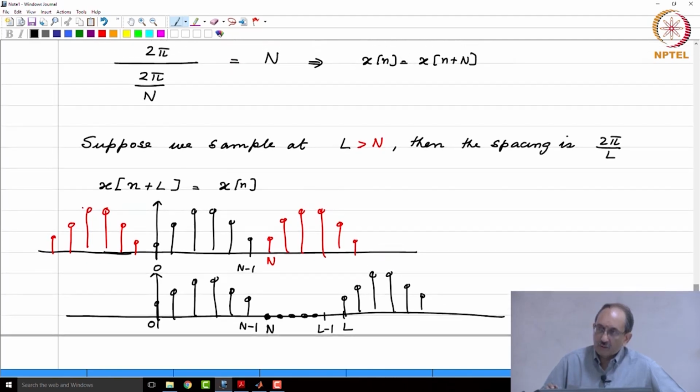When you say time period, can you? No, remember we are sampling in the frequency domain, correct? In the frequency domain your interval is always 0 to 2 pi. So within 0 to 2 pi, what is your sampling period? You need 2 pi by cap n at a minimum, right?